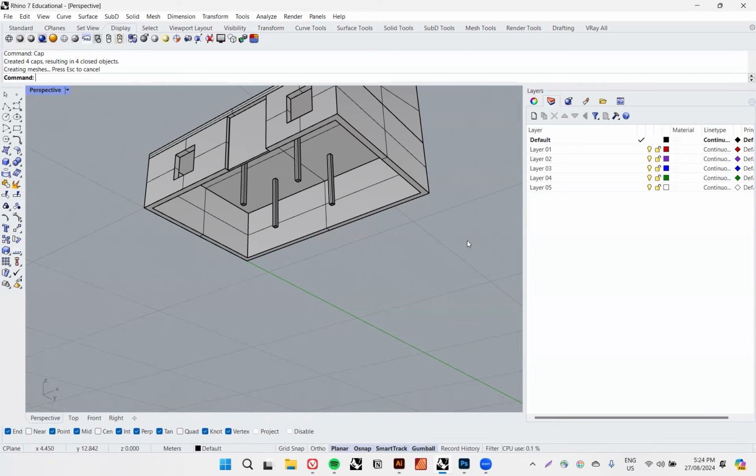So when you come into Rhino, we forgot to touch on that. There are 6 layers automatically created. The most important thing for you guys to have a smooth workflow is to work within layers. I will name each of these layers based on what I'm doing. So I might have a layer for my roof, a layer for all of my columns, for windows. And once you start making bigger files with actual rooms and actual windows and furniture, you're going to have sublayers within sublayers, but it's so good to keep it organized.